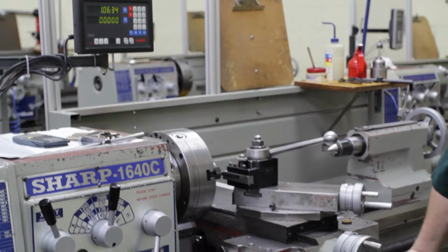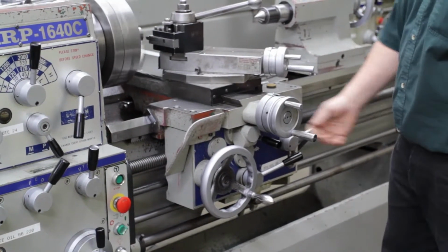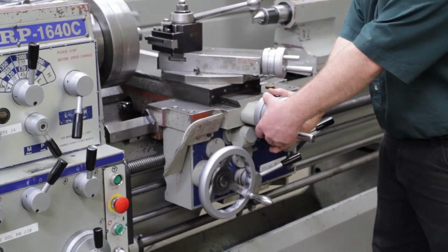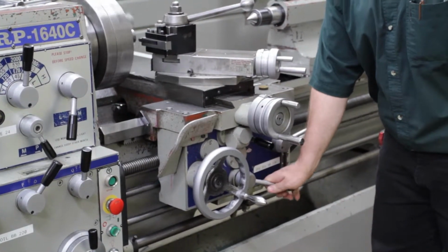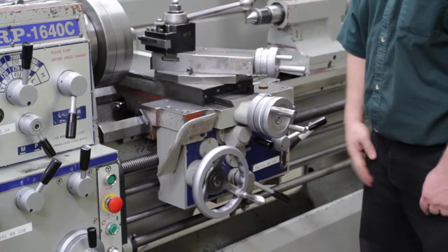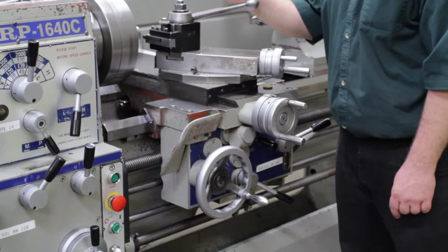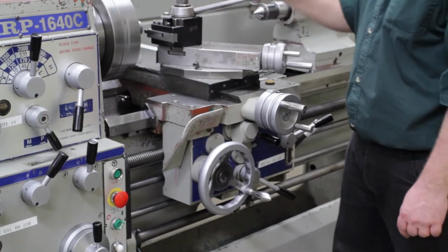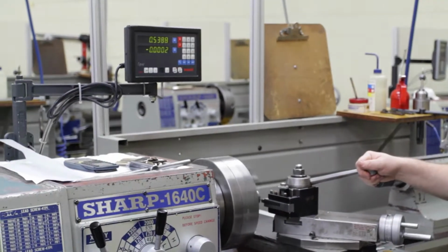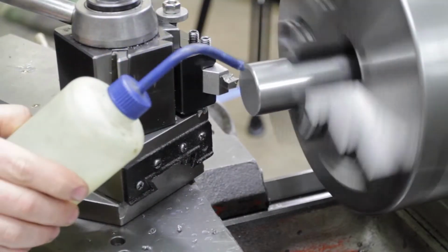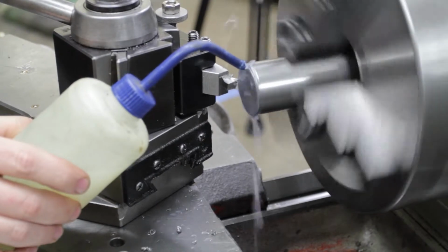So I'm going to restart the machine. Remember, up is forward. This handle is up, so I know it's going to control this hand wheel. So if I push down the feed lever, you see that handle's turning. So while that handle is turning, it's feeding the tool bit across the workpiece. And you'll see on the x-axis that the numbers are counting down. It's a good idea to use a little bit of coolant. It keeps the tool from overheating, and it helps aid the cutting process.